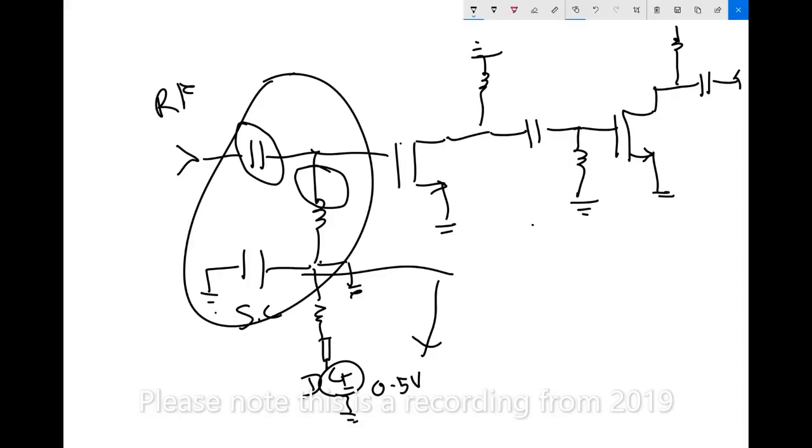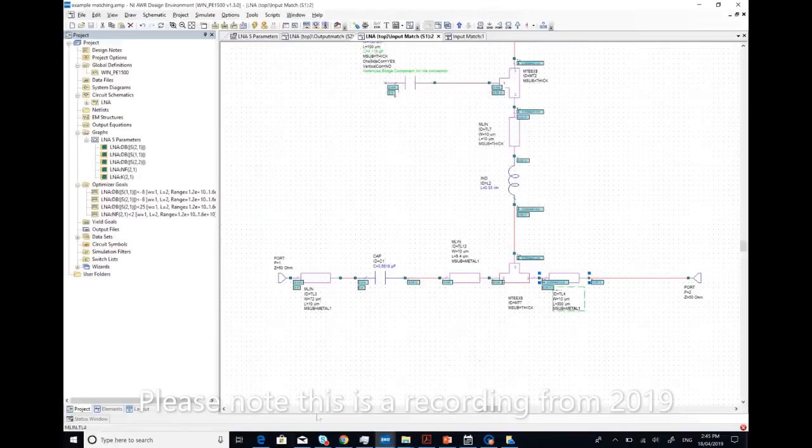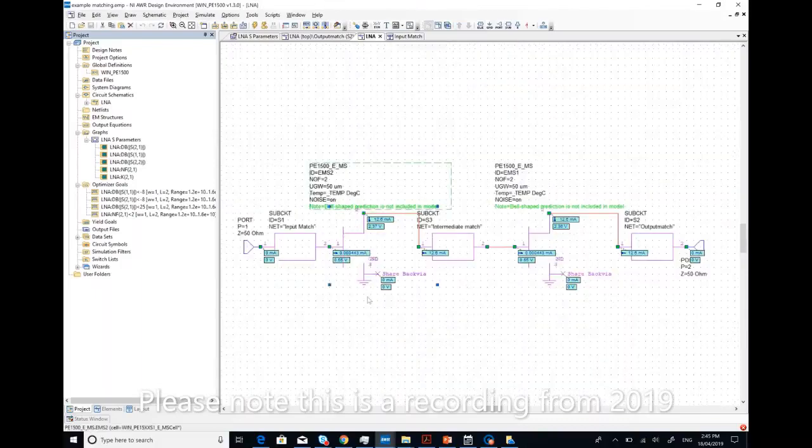So you can theoretically calculate the C and the L from the equations that we've discussed before for 14 gigahertz. Now to do that, you need the impedance at this point, right? So you can look at that impedance on a Smith chart for the transistor if you want. I'll talk about that probably in the class, but maybe I'll just show it to you guys now quickly. So if I want to look at the transistor, which is the transistor here, I can plot this on a S parameter,